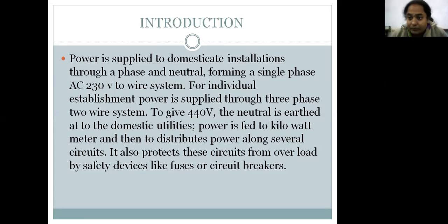Okay, so usually a normal single phase connection will accommodate one motor, one heater pump and a few bulbs, and a fridge, that's it. So if the load is increased, like you're using multiple ACs at a time, then we have to go for triple phase. So the power is distributed that way.